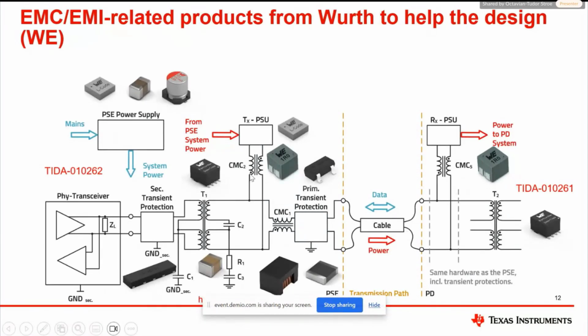Now, you might see this is a common mode choke, but you have the two dots and you might think, okay, this might be a weird connection. Well, this common mode choke is wired in this way because it prevents any differential DC current from saturating the choke, so that the signal that opposes the impedance of each choke winding is thus decoupled. Sometimes we have additional differential mode filtering, which we can add here for the DC power, using additional inductors that can be placed either before or after common mode choke 2 or common mode choke 5.